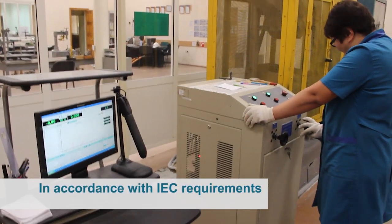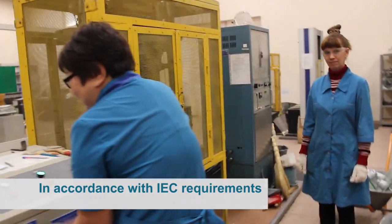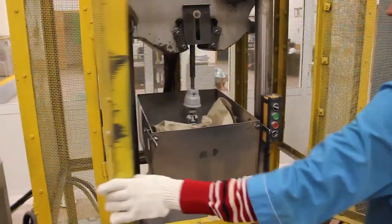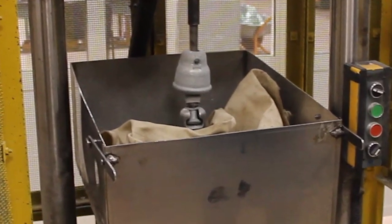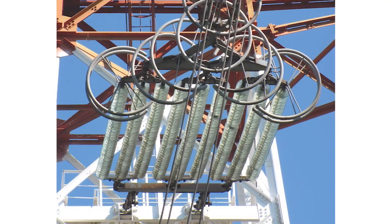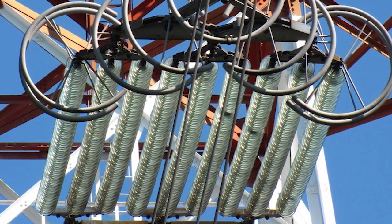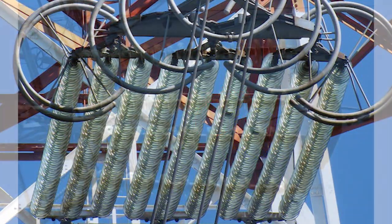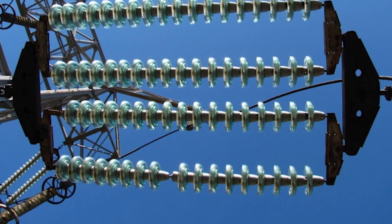According to IEC requirements, the insulator residue should withstand no less than 80% of specified mechanical load. Destructed toughened glass insulator is visually determined by the absence of visible insulating part, which is impossible for annealed glass and other insulating materials, when destructed insulator can be determined only after removal and testing.